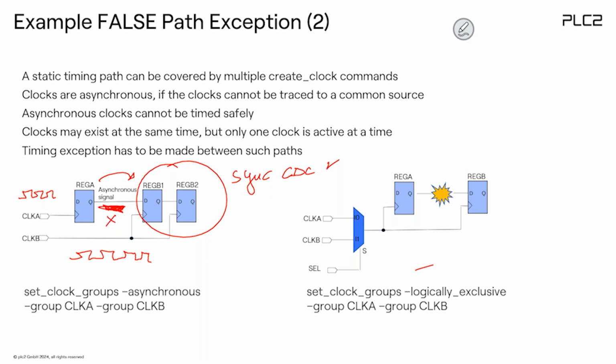Or look at this application. So we do have a clock multiplexer, for example, now in an FPGA, with clock A and clock B. This means if you switch to clock A, you will get clock A here. If you switch to clock B, you will get clock B here, something different. But you know what happened? So this is A, and then you switch maybe right here. This would be the select.